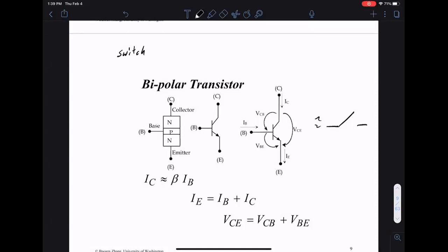Whereas MOSFET is lower loss. MOSFET is a lot more efficient because it's voltage driven. At the gate, you apply a voltage, and you have an insulator between your gate and the rest of the transistor. But it had problems tolerating high current in the past.